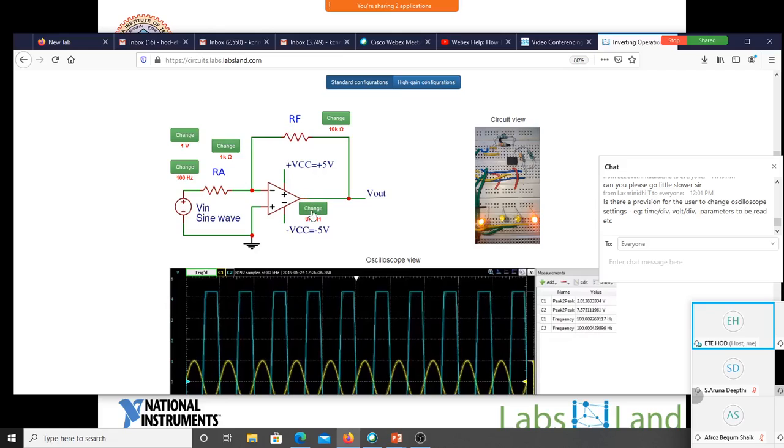So of course, here we have one more op amp, which is the usual μA741. The other one, a high frequency op amp, we have also considered to showcase how the open loop gain of the op amp matters a lot in the closed loop gain and the closed loop bandwidth of the system.